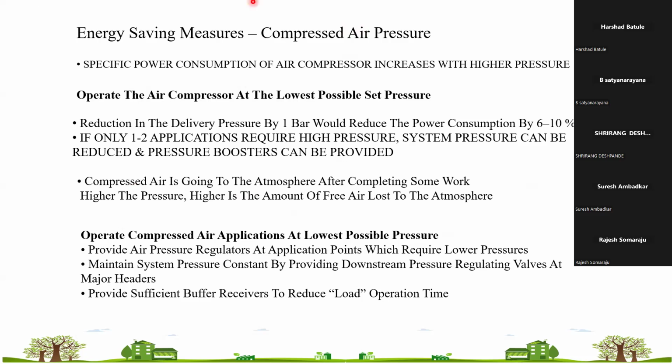If you are allowing cool air as an intake to the compressor, you are allowing the compressor to perform at desired or standard conditions. But there is a thumb rule: if you increase your intake air temperature by 4 degrees Celsius, your specific energy consumption increases by 1%. That is performance deterioration over temperature.